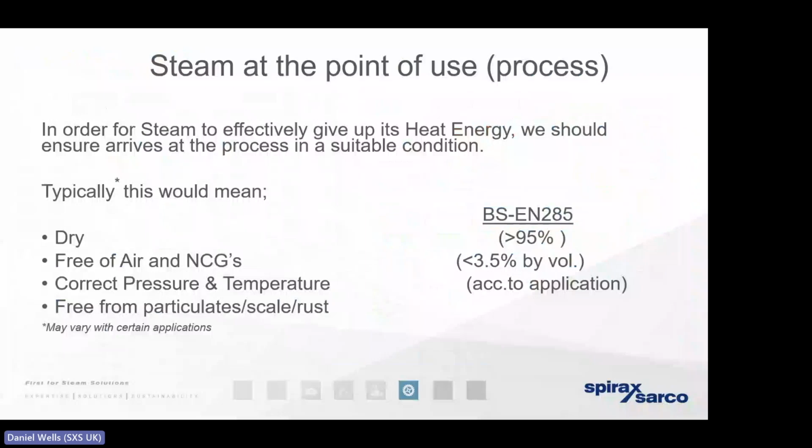And as far as HTM 01-01 is concerned, that generally uses a standard we refer to as BS EN 285, and that's calling for the steam to exist at a dryness value of 95% or better. So that tells you, once again, how critically important it is that we're removing that condensate using the appropriate steam trap.